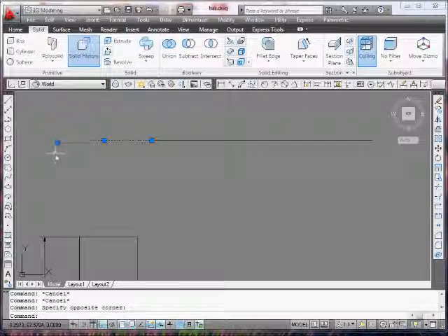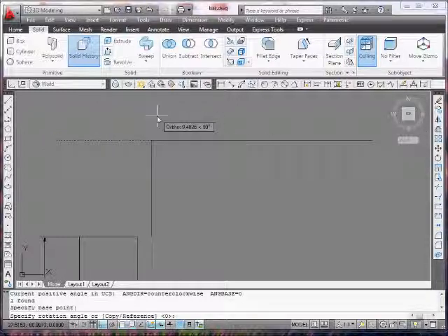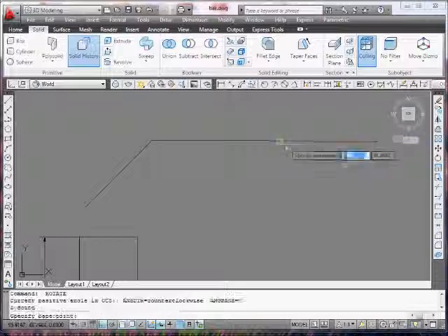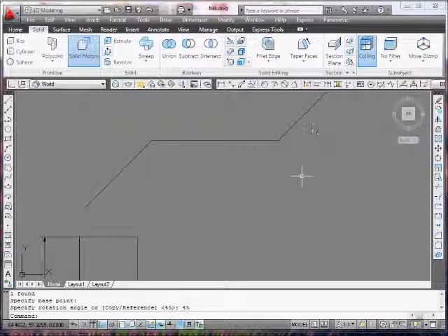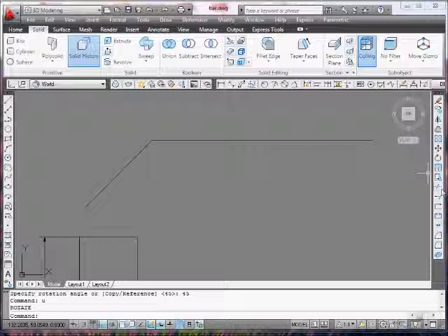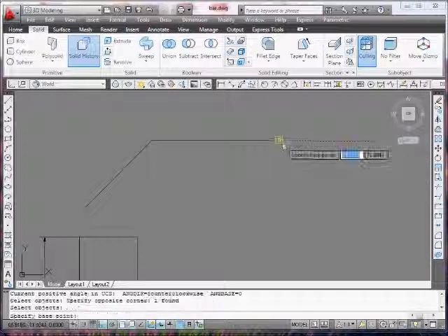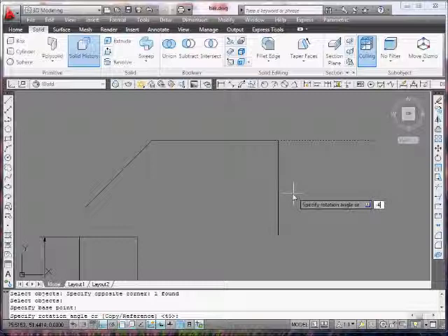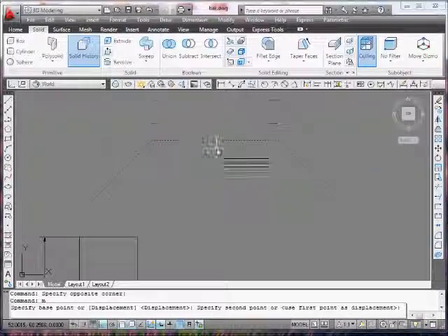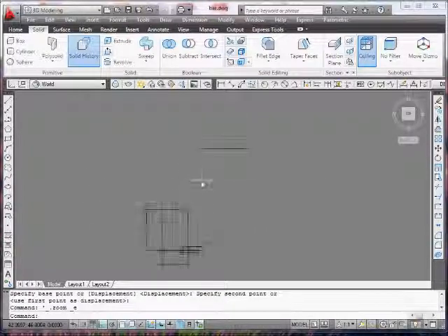I'm just making a straight line because later on I can just rotate these without a worry. I select the edge lines I created, and I'm going to rotate them 45 degrees. Oops, that should have been negative 45. So I go to rotate, negative 45. Move up like so.